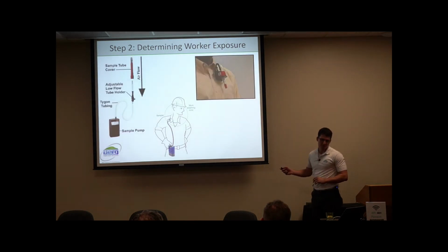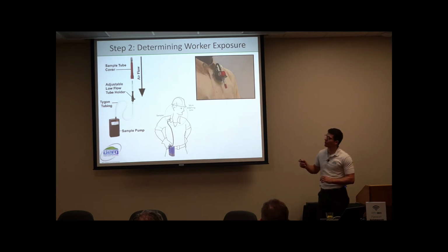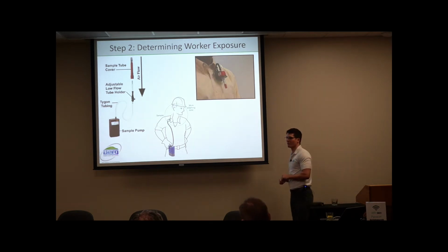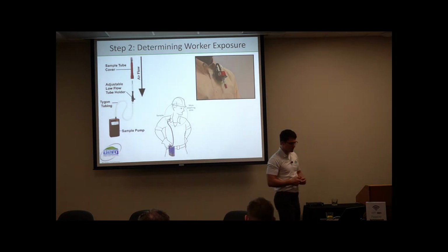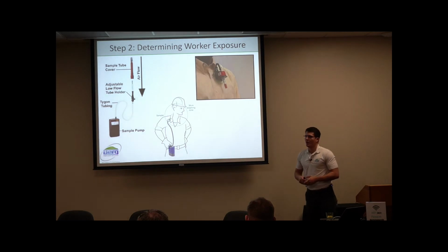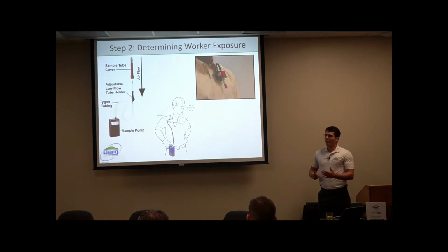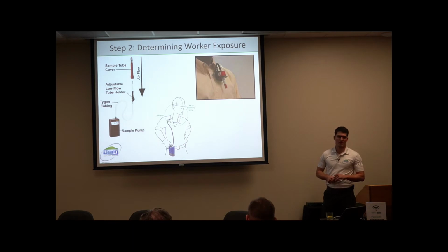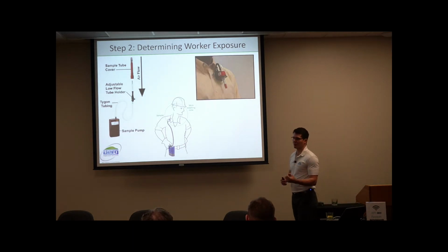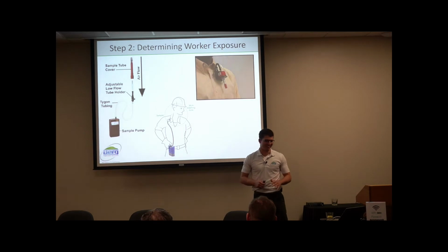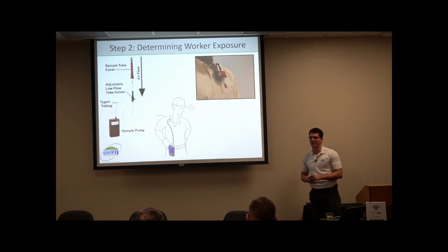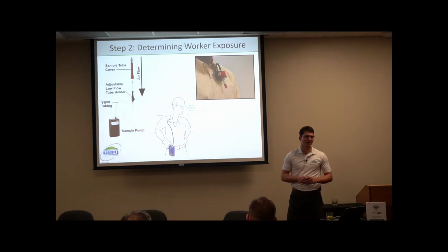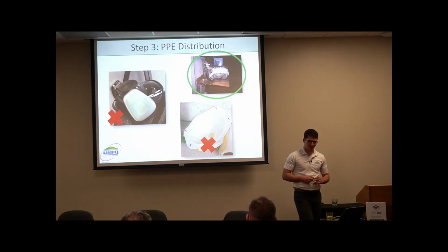So step number 2, determining your worker exposure. Right up there in the right corner, you see the cyclone. That's for respirable particles of crystalline silica, by the way. And so you would typically strap up your employees, and obviously let them know the purpose and why they're being strapped up. They're always asking me on the side of hearing conservation, hey, is this recording my words, right? No, it's not. It's just recording the intensity. And then same thing in the case of air, you just want to let them know that you're sampling to make sure that we're below the regulatory limits.